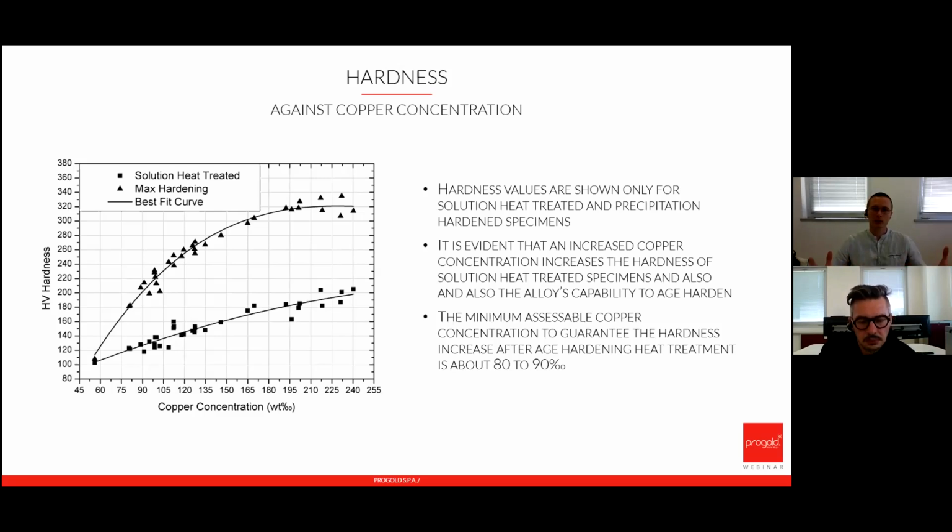So in a certain way, you take a lot of energy and you put it inside the material. And this energy is helpful during the annealing process because it helps to regenerate the grain, so to create new little grains. So the more you deform, the more you will get small grains after annealing, obviously at the same annealing condition.